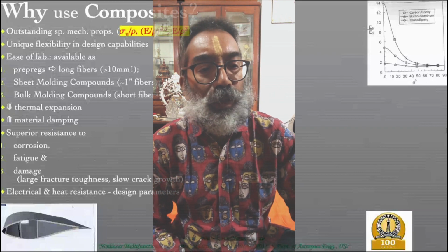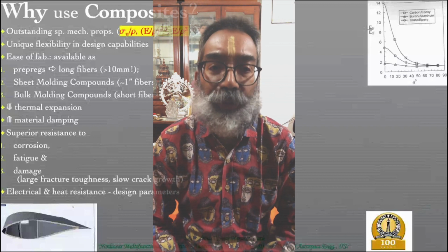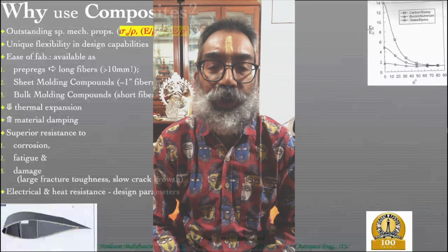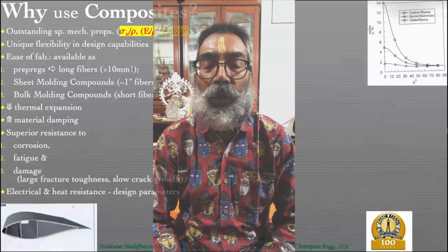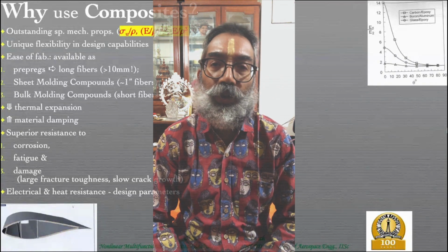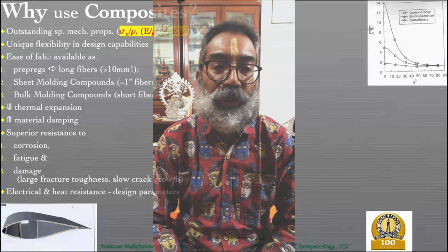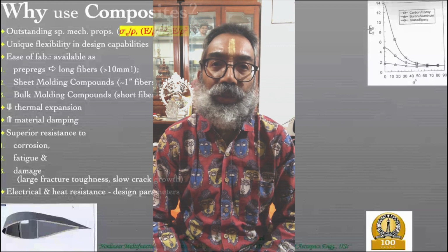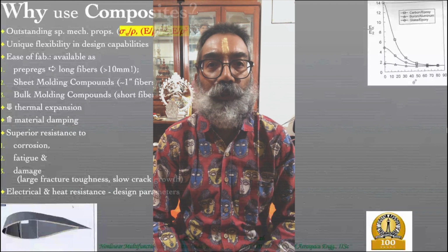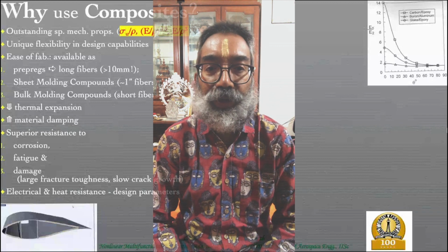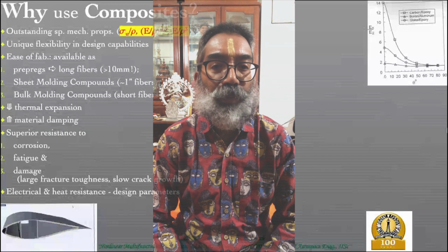Yeah. So the primary reason we use composites, of course, is their relatively better specific properties compared to metals which were conventionally used, especially aluminum alloys, in terms of the specific strength, sigma U by rho, the specific stiffness, more so in a dynamic situation as a square root of E by rho, and most importantly, the deciding factor being in the stability-based design, the performance index being E by rho cube, because of their lower densities and rho appearing as a cube in the denominator here, that becomes a primary deciding factor over many of the conventional materials.